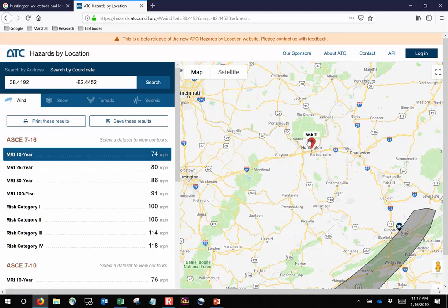This is the 10-year wind, the 25-year wind, the 50-year wind, the 100-year wind. What the spec body has done, and this has changed from edition to edition, is because LRFD is becoming the norm, they reported these wind speeds such that they're already factored. If you look at the LRFD load combinations, the load factor for wind is 1 because the load factors are already built into the load.